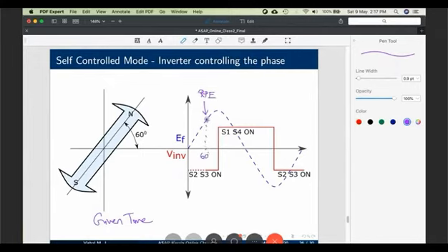Now if I know 60 degree, what all things can I say? 60 degree backwards, I had my EF positive zero crossing. 30 degree from now, I will have the positive peak of EF. 120 degree from now, I will have my zero of EF, which means if you know where the rotor poles are currently, you can reconstruct the EF wave. The dashed blue lines you see are the EF wave. So just by having one point in the locus, you can reconstruct your excitation voltage waveform.